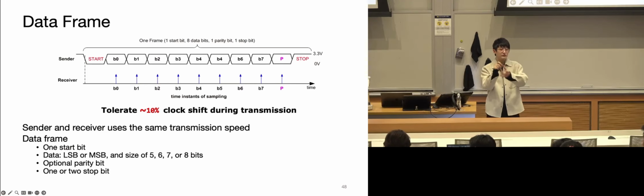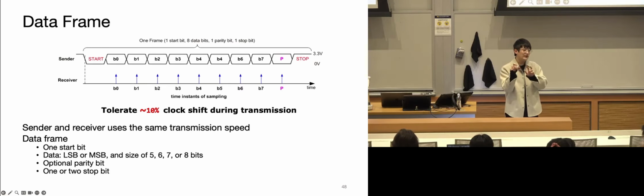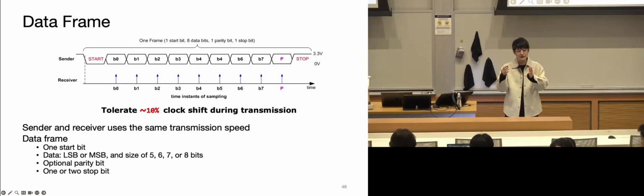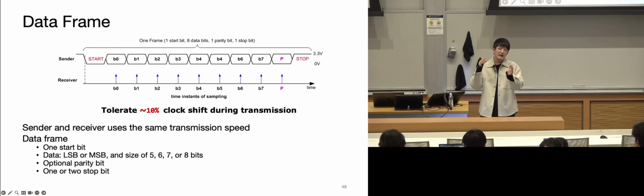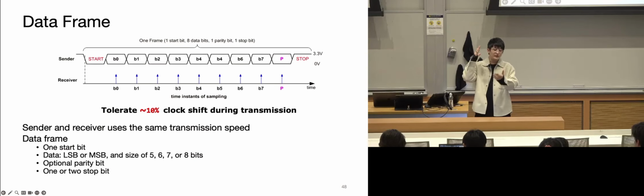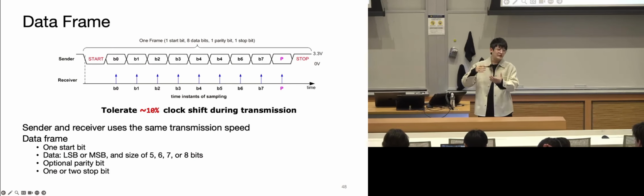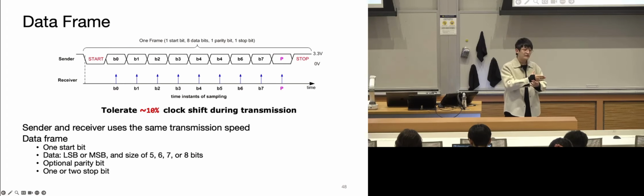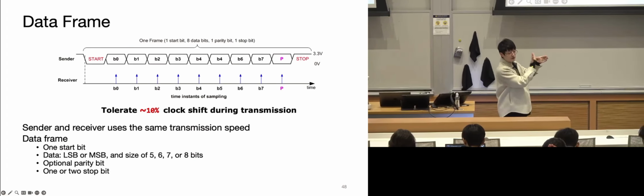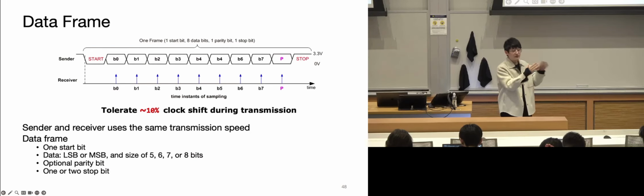Yes, so it's true that there is essentially an unavoidable error however fast you oversample. There could be a shift of one clock cycle, right? Which is why, under oversampling, it always samples in the middle. So if I sample 10 times faster than the signal coming in, the actual sample of data is logged on cycle 5, to give actual wiggle room or tolerance